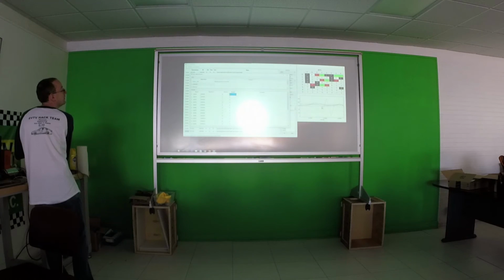And we use the DBC editor like that to set these up so we don't have to do it again. This shows another neat thing the DBCs can do. We have the gear selector in 228. And the gear, down here, we have a value table. When the gear changes, a gear value of 1 or 2 is neutral, 3 is reverse, and 4 is drive.